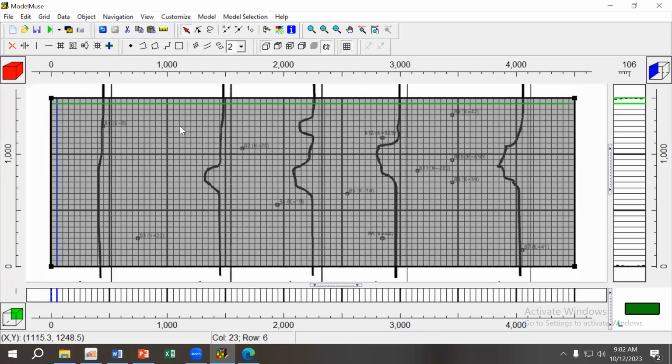But you get something like this. Now the next step, remember, our objective is that we have several steps here. The next step is to define the hydraulic conductivity zone. Here in our equation, we need to define this, and then after this, we need to define our boundary conditions: recharge, pumping, and river. So let's start with this one. Let's define our hydraulic conductivity.